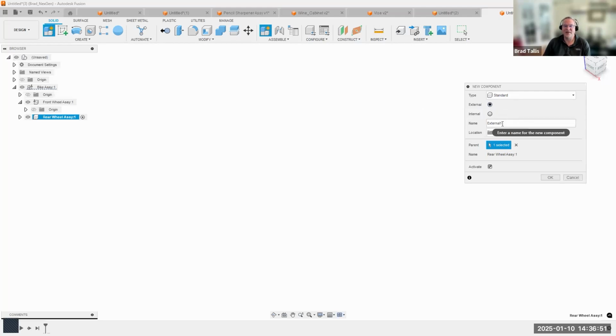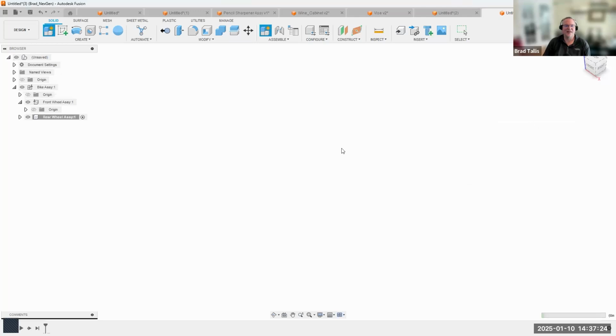And you'll notice when I do that, it allows me to give it a name. I'll call it pocket, right? And then it's allowing me to pick a location. When I create this component, it's going to save it for me automatically into a particular location. In this case, I'm in my webinar assemblies webinar location. And then I can also pick a parent and all that kind of stuff. I'll just leave it at the top level. In this case, I'll say okay.